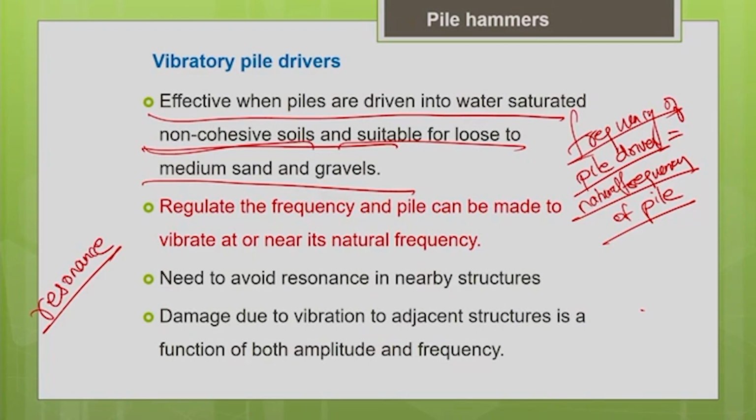That is why even for tougher soil conditions, nowadays you can use a vibratory pile driver, because of this advancement in technology due to the invention of the resonant pile driving method. You should vary the frequency in such a way that it matches the frequency of your pile. So this is one positive effect of resonance.